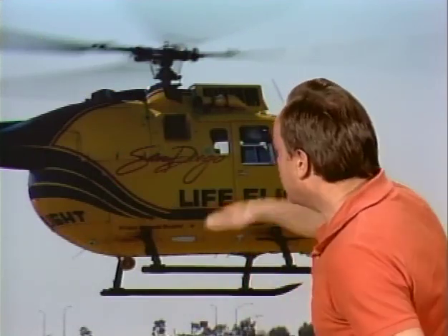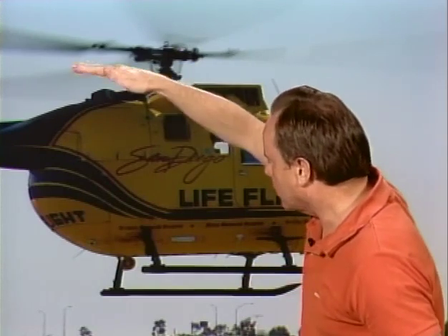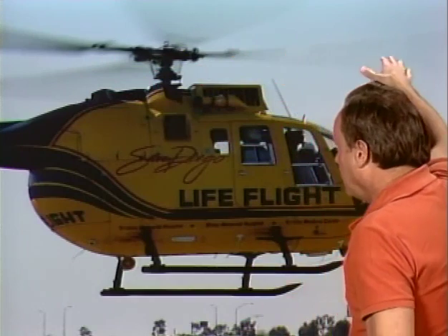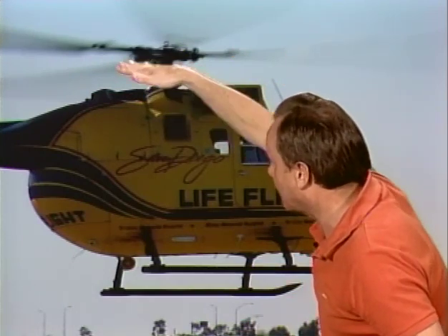Now, let's assume you're flying along. There is a downwash effect as the helicopter is flying along, and there is a greater downwash effect through the aft part of the main rotor disc. The reason for that is, of course, as the helicopter starts this front air going down and flies through that downwash, it gets greater at the aft part because the helicopter is moving into that air. Now, what is that effect called? They ask you on the test, and the answer is that effect is called transverse flow lift.